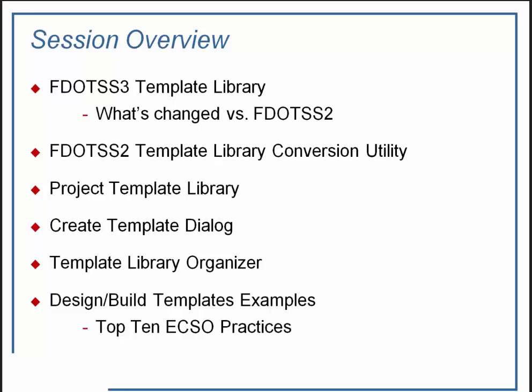A lot of things have changed as far as the features and point definition styles. If you try to bring up an old ITL file in the new software, you're going to get nothing but white lines, so we need to convert those first, and our utility works pretty good. I'm going to demonstrate that.